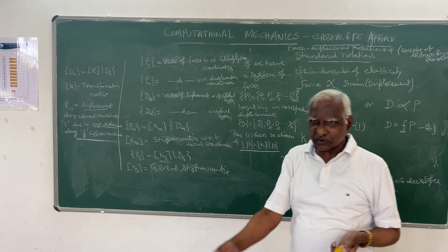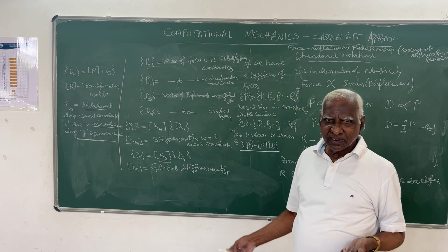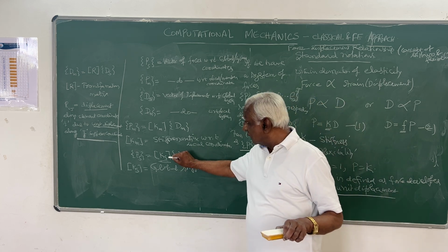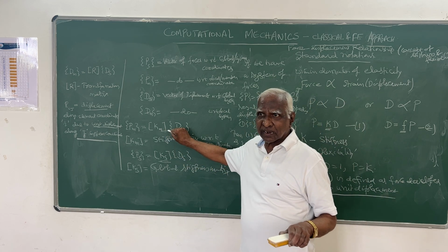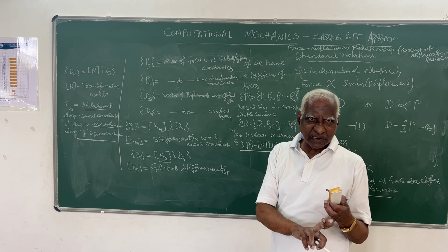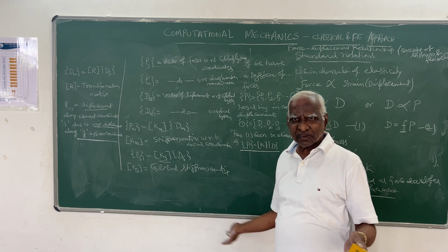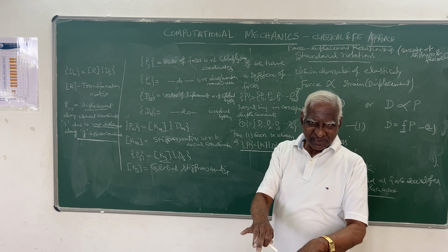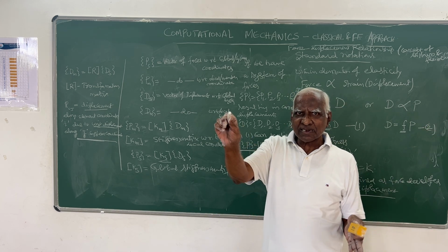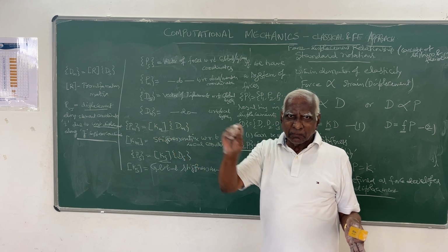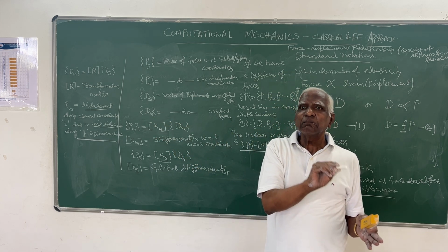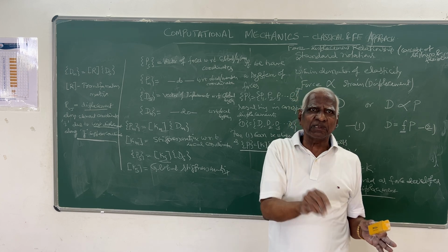Here, the classical approach, if you have another 10 minutes, I can develop the Km stiffness matrix for a beam element or one truss element. Plane frame also, combining beam and truss, you will get a plane frame. Because truss is only axial, beam is shear and moment, and plane frame has both axial and shear, beam.